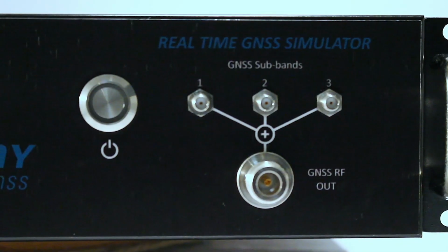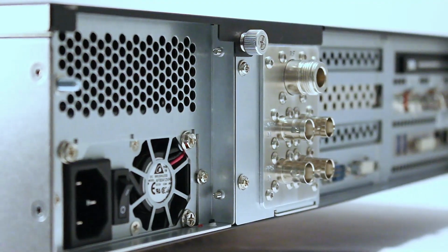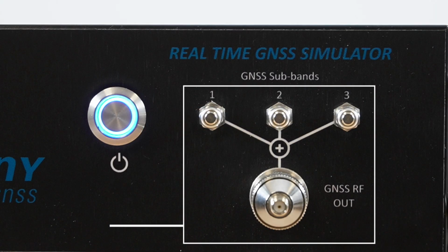The Constellator setup consists of a main platform called the server that plays simultaneously the role of the big computation unit and the RF signal generator. It embeds a specifically designed motherboard to generate IQ values at high speed and an RF block to convert them into GNSS signals. As you can see on the front face, the TX board provides 3 independent RF outputs plus 1 combined output. To configure and monitor your simulations, Constellator provides a clear and straightforward graphical user interface.